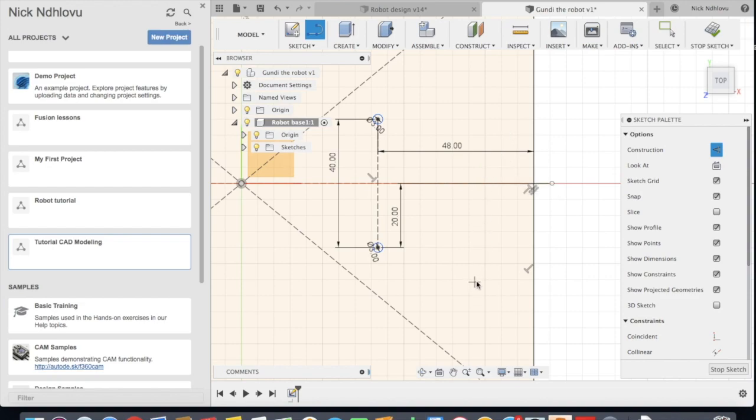Or I can just simply click here, hover on this line. So I'm going to hover on this line and you will see, can you see the dotted blue lines? Which means that is the same position, it's in the same height. I'm going to click here, left click, then I'm going to drag it to the top. I'm going to make it vertical, and then here it's going to snap. So it means, can you see that square highlighted blue or turquoise color? It means that it's in the same height. It's a point of special interest.